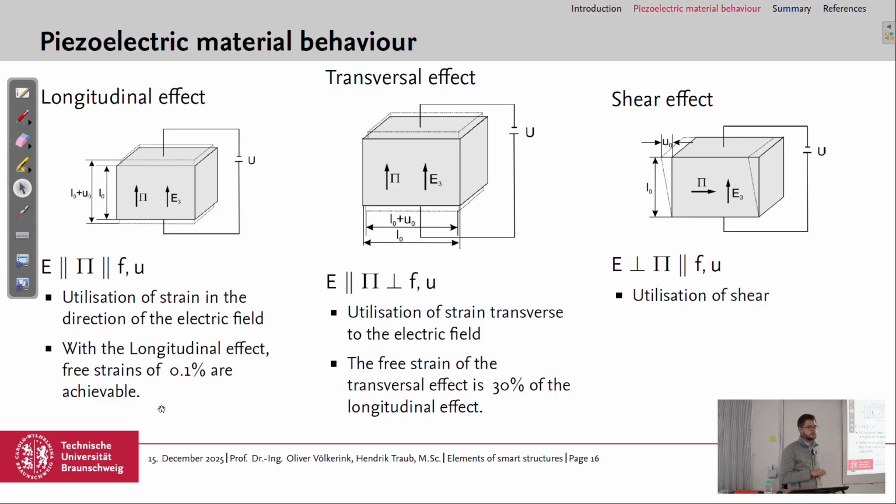So this is the range we can achieve. This is not that much, and therefore we will have tomorrow a lecture on displacement or stroke amplification. So how can you use these piezoceramics with some additional structures to amplify the achievable displacement to make it useful for technical applications.